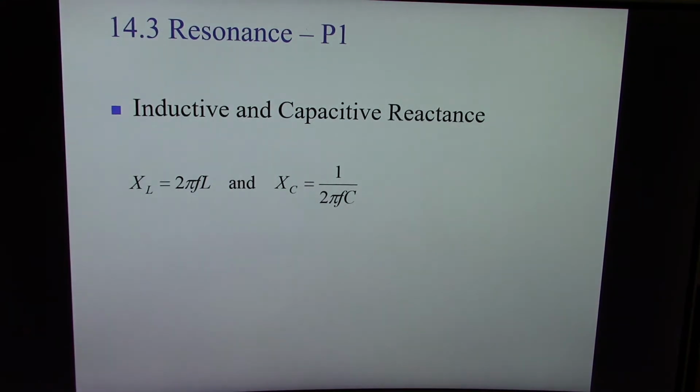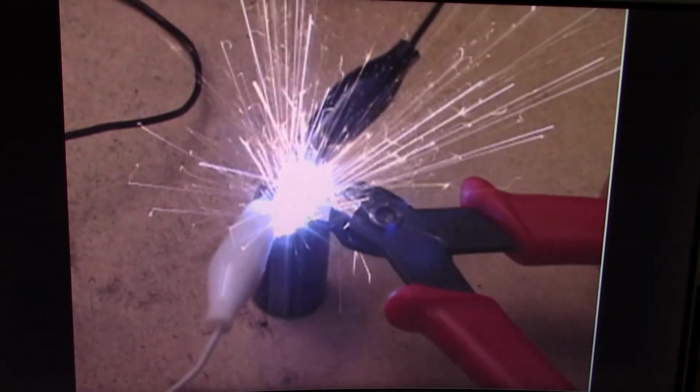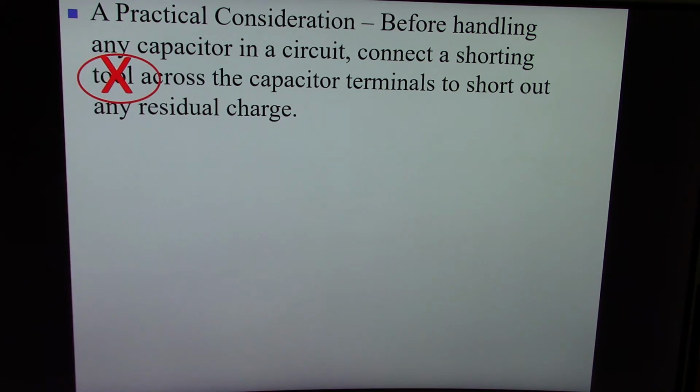And obviously, throughout my career, I've had a few of these things explode. I don't think I've ever done one myself, but nevertheless, when they explode, these capacitors are filled with some kind of oil-like substance. The stuff all spews out, and it's a fine mist of some carcinogenic oil that a person will have all over their body. So you don't want to put a tool across it.